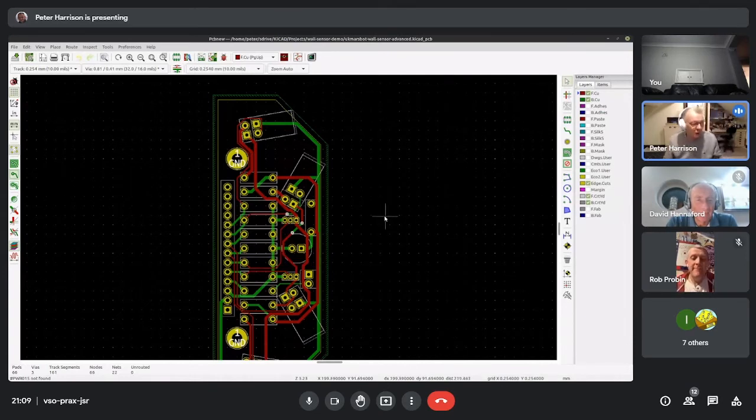So anyway, you can define your board outline. There are some constraints compared to Eagle. It's not so easy to do rounded edges and things like that. And you have to, and it's not, what's the right word? Can't think of the right word. The nodes at the ends of the lines are not connected. So if you pick up one of these lines and move it, it will not necessarily be connected. This is an annoyance, I confess, apparently to be fixed in 6.